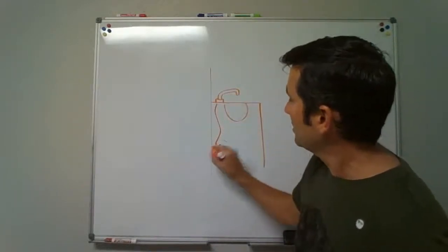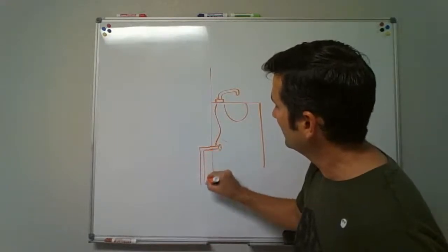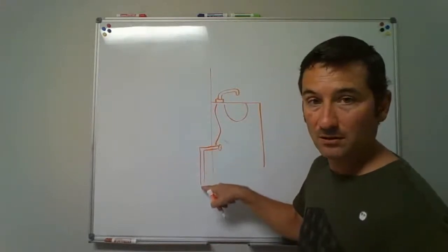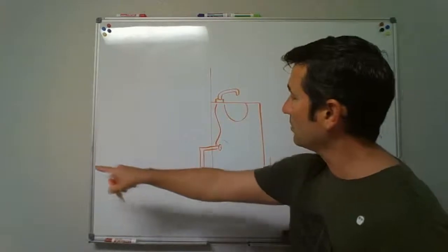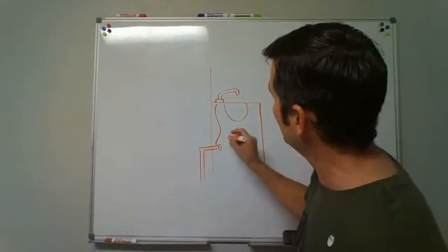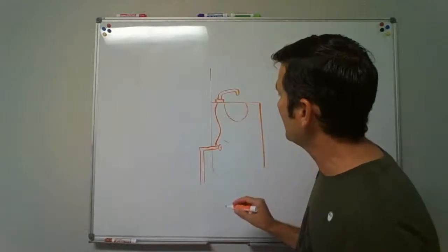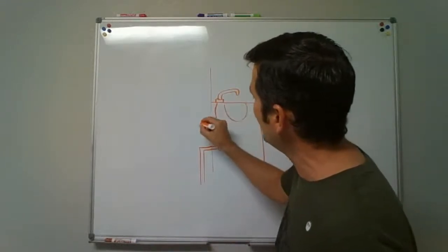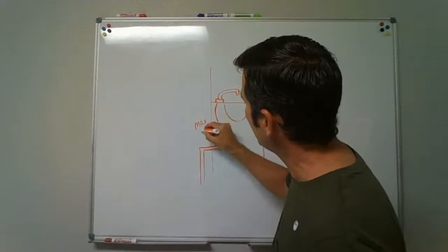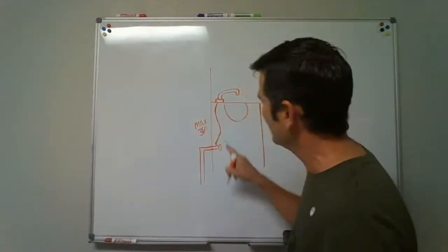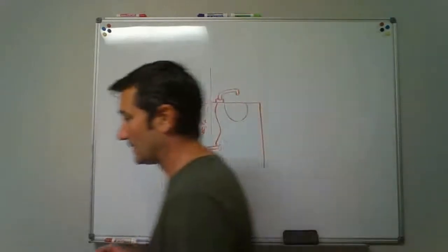Coming out here, all this is water distribution piping. Okay. It's under here. You got water service, water distribution, and then you got these little fixture supplies. Now, they say this line here can't be more than a max of 36 inches long. Okay.